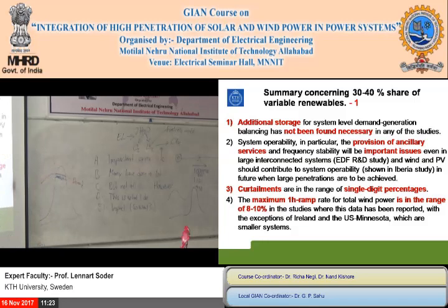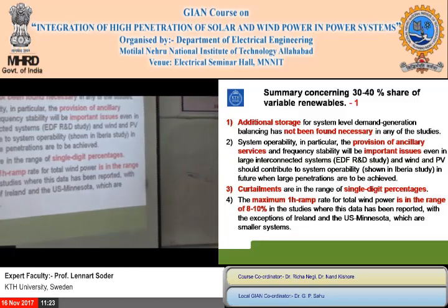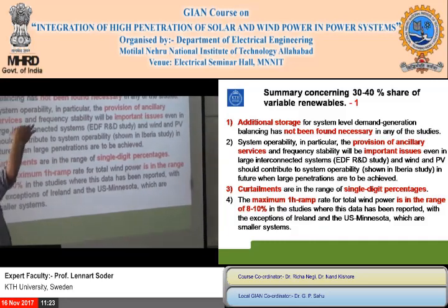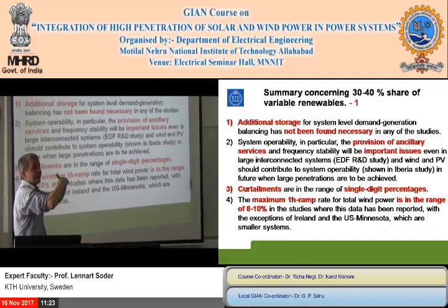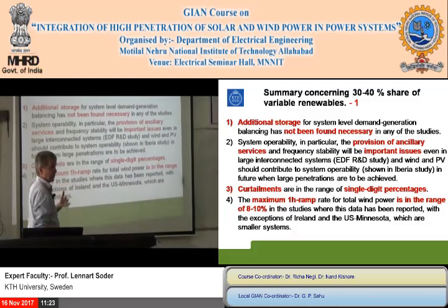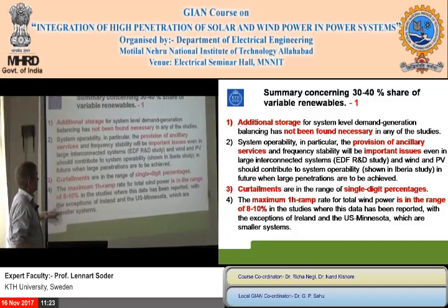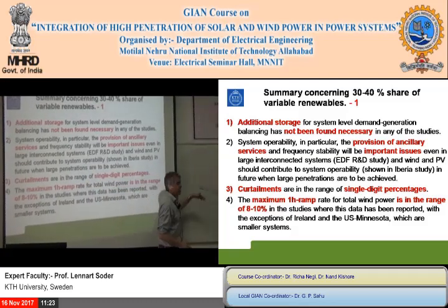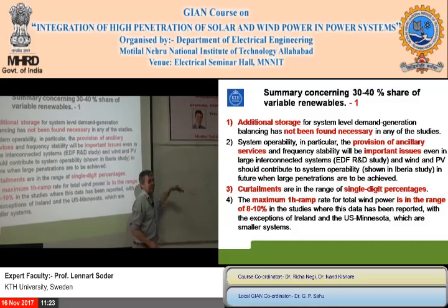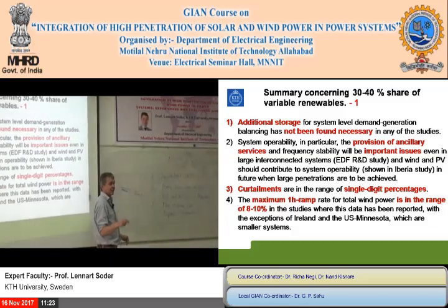So there is, of course, big value in having frequency control when you are curtailing. Don't curtail and just cut it to a certain level. Curtail it and then make it active in the primary control. That was studied, both in this frequency stability and in this EDF study. But the important issue is that it's not necessary to do it, but it's smart. And I think you have to separate between necessary and smart.